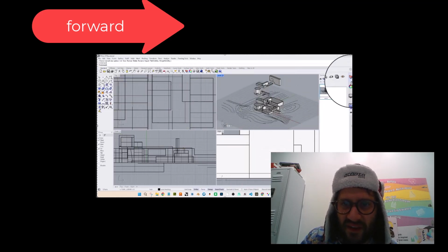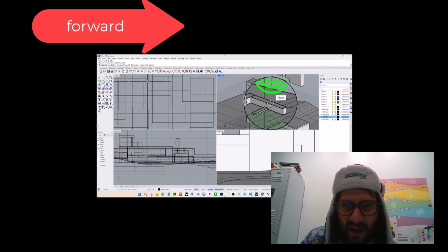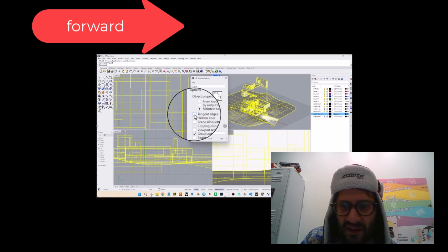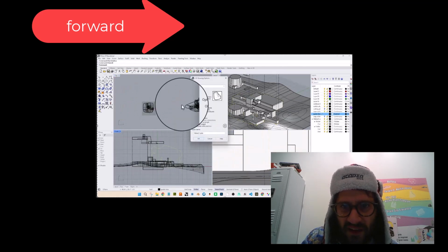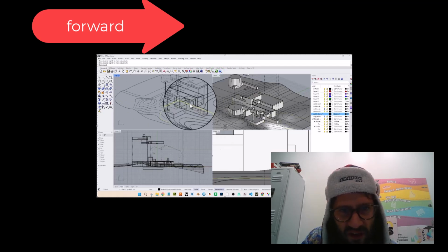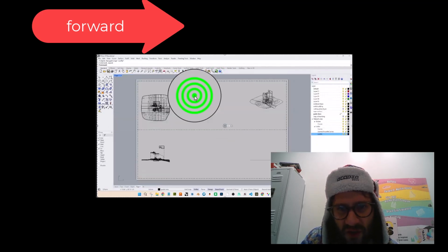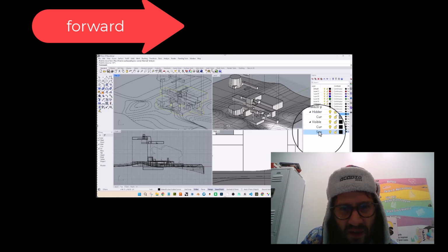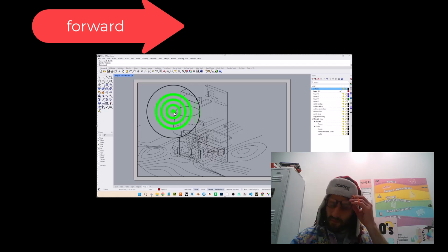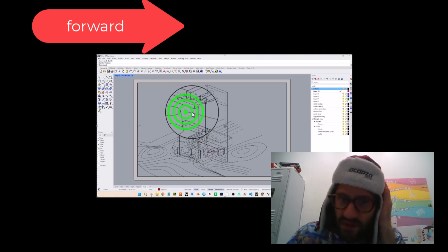I made a copy of all this, so I didn't ruin that. And then I made a layer for guidelines, like these vertical lines here that would be shown in an exploded axon like that. I do some mesh offset stuff. I make a mistake the first time, which is which layer I make the 2D from, but mesh outline. Maybe I said mesh offset by accident. Mesh outline will take an outline of either a mesh, like a 3D shape, or a group of 3D shapes,